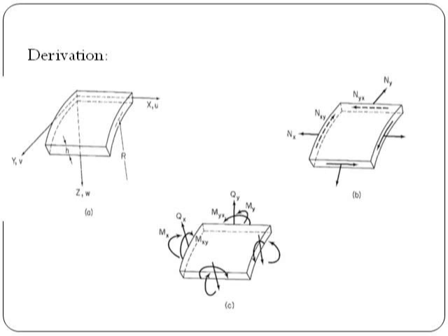Displacement of the shell are described by their components u and v and w in the x, y and z directions respectively, as indicated in the figure. The forces acting on the shell element consist of the in-plane forces depicted in this second figure B. It is depicted in this figure all the forces acting on the element, and the transverse shear and bending are indicated in this figure.